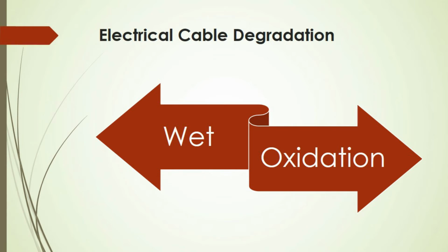Initially, only voids and minor defects will form on the cable. However, the formed cavities will propagate through the polymer insulation and expand into tree branch forms over time. Humidity, when combined with an AC electric field in a type of environment seen in underground cable installations, can cause water trees to expand. And when the electrical stress on developing water trees becomes too much for them to handle, an electric tree forms. Water trees' time-dependent growth and extension can drastically diminish the usable life of power cables.